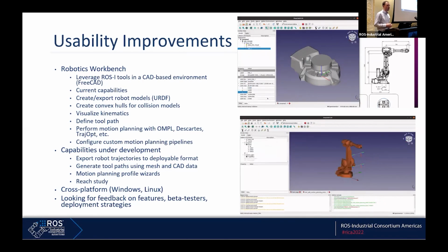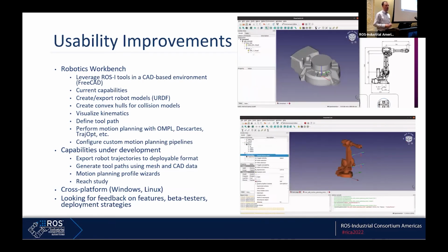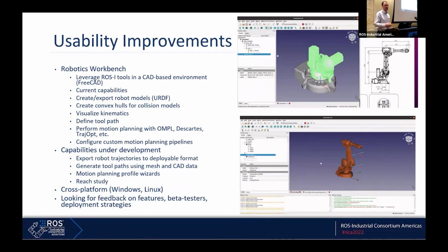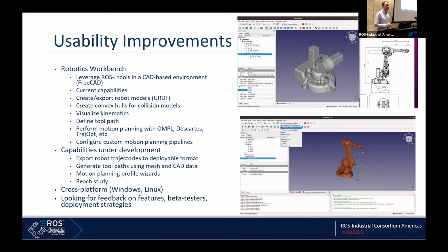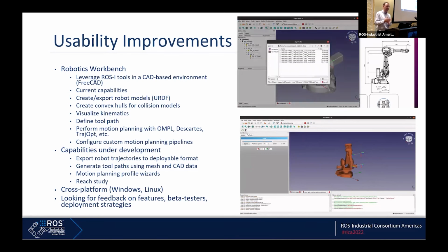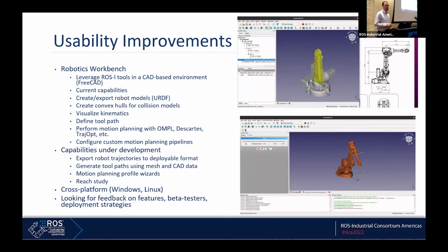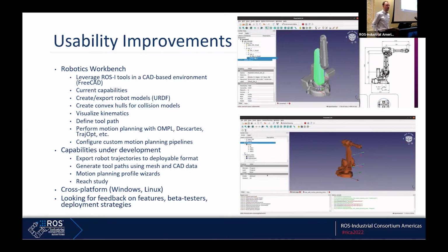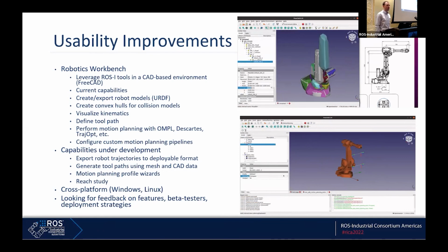We've been leveraging that quite a bit for generating convex hulls for complicated shapes, and it works reasonably well with some tuning. What we don't necessarily have right now is something to expand those convex hulls like we were talking about, but I think that's something we could build in relatively easily, and that's an important piece, right? You don't want your collision models to be exactly the same as your visual models, just a little bit of a buffer in there. So that's great feedback. All right, thanks.